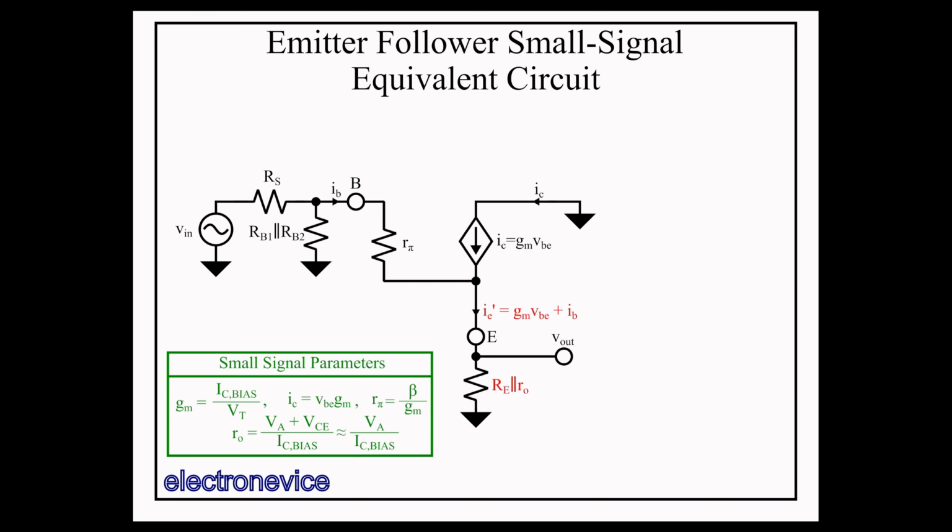This can be a bit confusing since I've called the collector current IC equal to gm VBE, whereas the true collector current is gm VBE plus the current through RO. However, since the currents are labeled on the schematic, you can observe them where they are in the circuit. Just be careful not to assume that one person's IC is the same as my IC, so to speak.